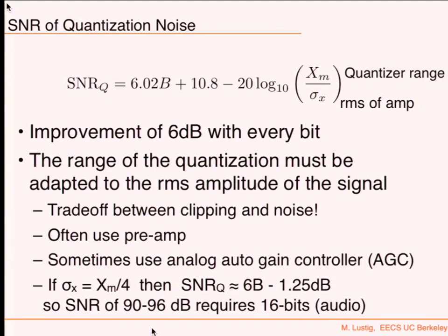Any questions? Yeah. What is the example for why is the delta x? It's kind of a trade-off, right? Because the RMS is kind of the root mean square, right? My signal does become bigger than this, right? So you want to make sure that you don't clip. When you clip, you're actually introducing way more errors. You never want to clip.